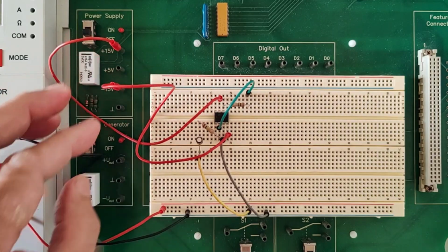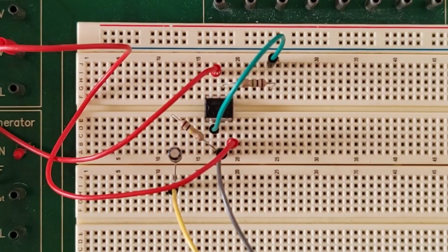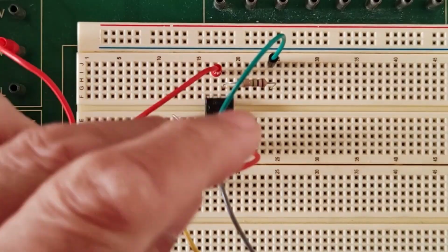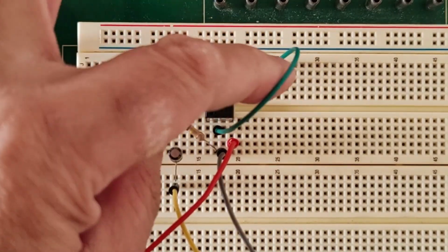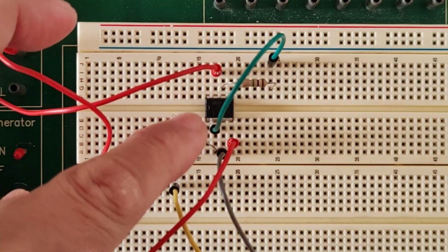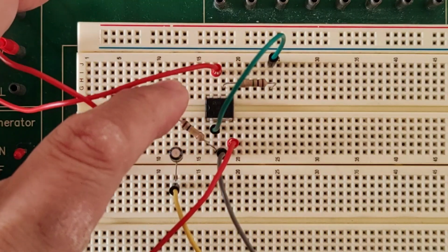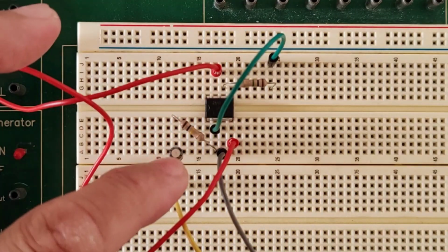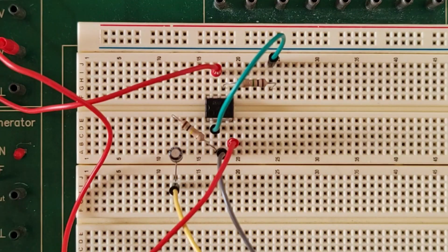Yeah, closer look if you want, you see from here, pin number 4, pin number 7, pin 6, jumper wire going back to pin 2. You get the 100 kilo ohm resistor here. This is your input resistor. Here's your capacitor connected to that leg of the input resistor.